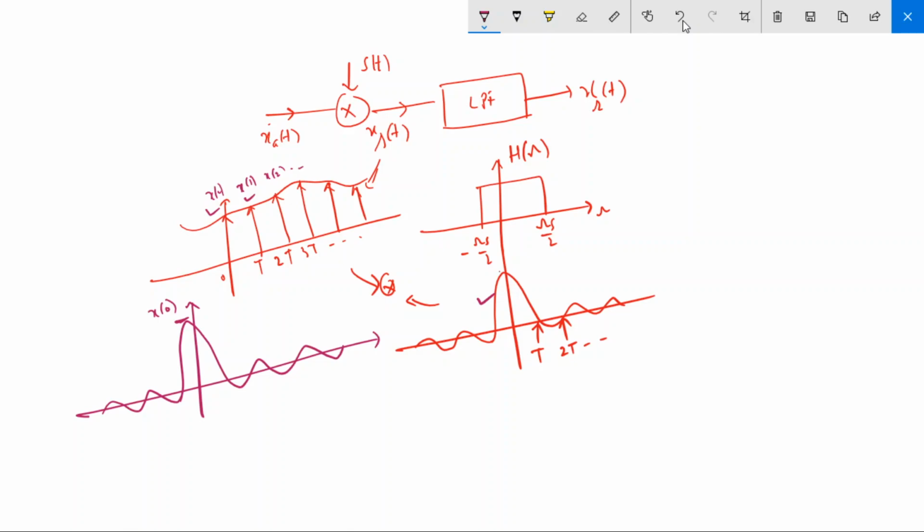So you scale this magnitude, you multiply it with x(1), it may be any value, 2, 1, whatever it is, and then you shift it in time by capital T, you are getting a second sinc pulse. So this is time T. It means you are getting a second pulse like this. Now the magnitude of this will be different than this.